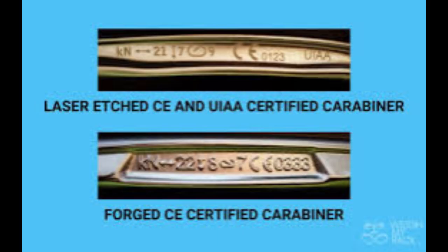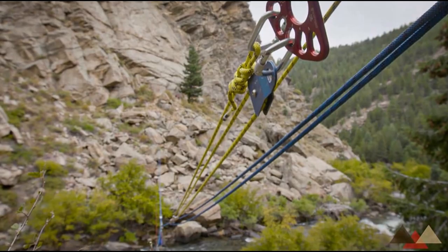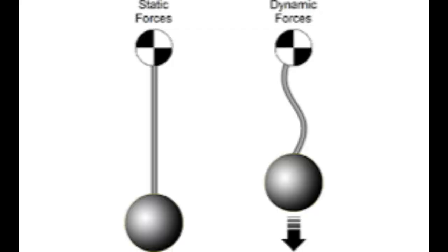When we tie a knot like a figure eight, we reduce that strength. A 30% reduction isn't unusual, which brings our 40 kN rope down to about 28 kN. And now, if that knot is the weakest point in the system, our system safety factor drops to something closer to 10.5:1, still safe but less forgiving.